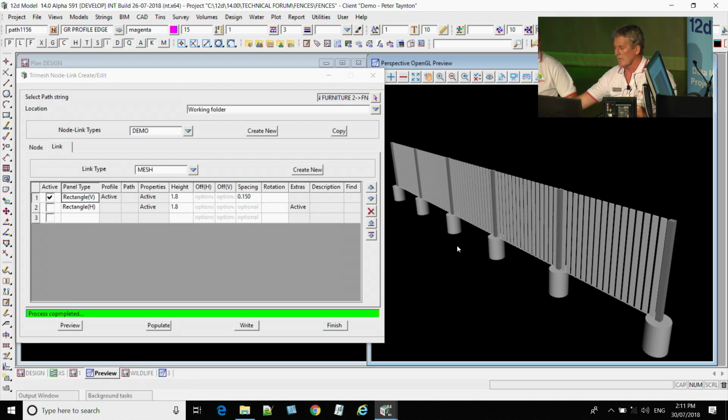So it's looking... I'm looking at doing palings. So if I wanted to go the other way, it'd be a rail. And if I wanted to do circular bars and that sort of stuff for weld mesh fence, you go to circular. The circular one does get a little bit heavy if you're doing small diameters and you want it to look good. So you may find yourself, when you do a few wires and things like that for construction fences, that you probably make it rectangular and maybe 10 mil by 10 mil, so it doesn't take up so much time or points in your data, of course.